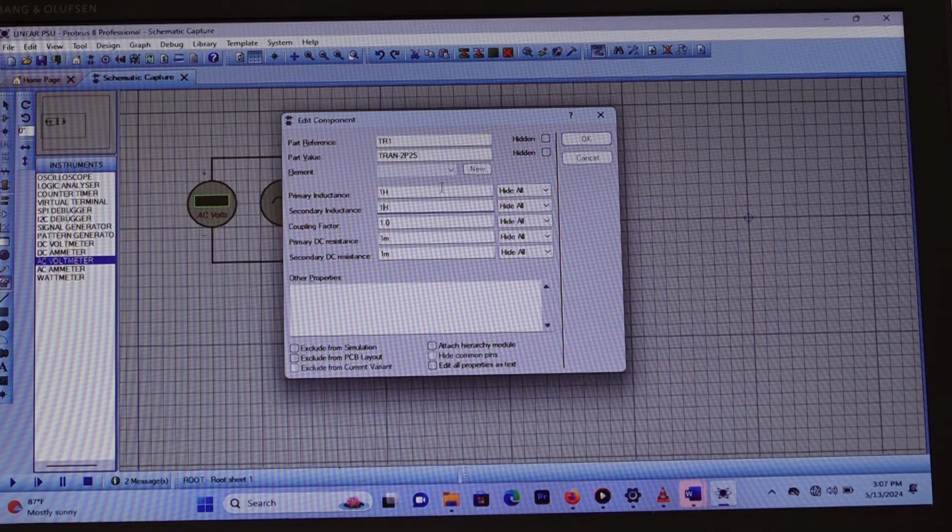So we have been given a chance to either make it step-down or make it step-up. To make it step-down, we have to lower the secondary inductance. It means reducing the number of turns. If you reduce the number of turns in the secondary coil, its secondary inductance will decrease, because remember that inductance is proportional to the number of turns.